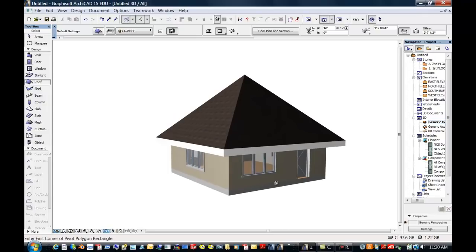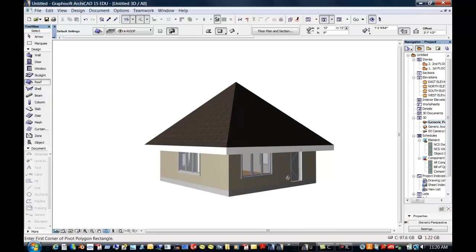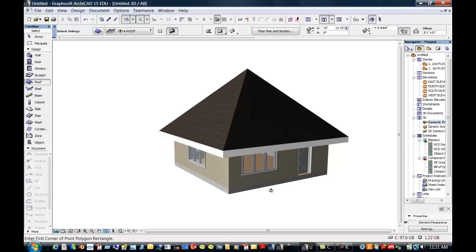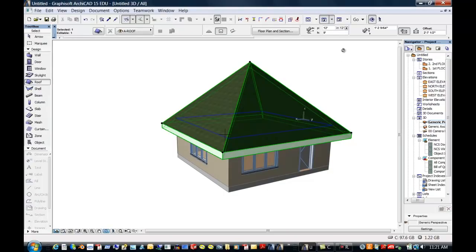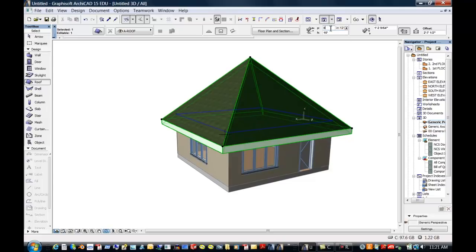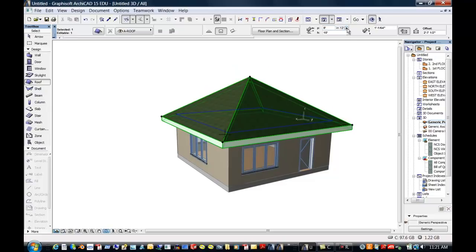One thing that happened is I believe that our walls are 9 feet, and I think the roof is now 10. I want to select all the roof panels and move that roof up. So I have roof over here. Control A selects everything of that particular component, and it did start, but let's change this and move this up to be at the 10-foot level, and I'm going to change this to be 8 so the pitch isn't quite 12, but I can also change other things about it. So we like that, and now what we've done is changed our roof.